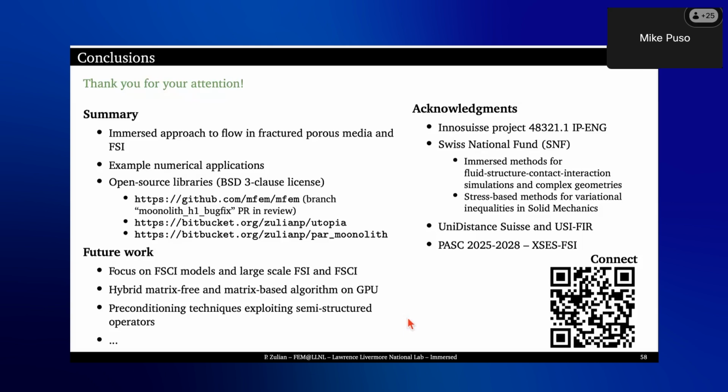Sorry. The way we'll go for the next couple of developments is to get rid of the monolithic formulation and really push on the fluid resolution, because this is where you need the resolution anyway to capture all the turbulence and other effects. So it makes sense for us to stick to this approach, but of course we are also ready to reevaluate if better things come along. The nice thing about the monolithic approach is that in terms of Newton iterations, it goes down very nicely.